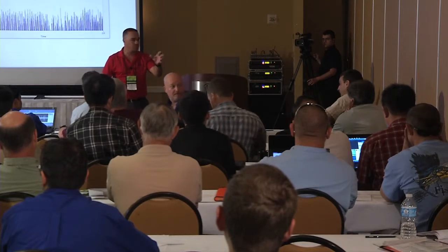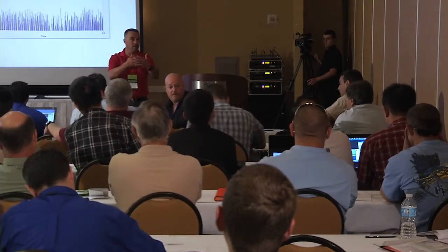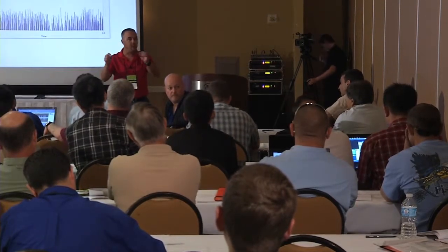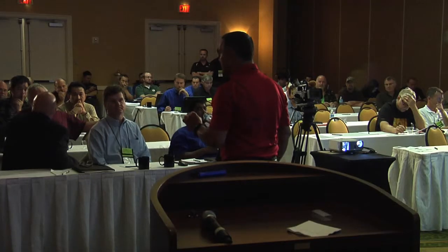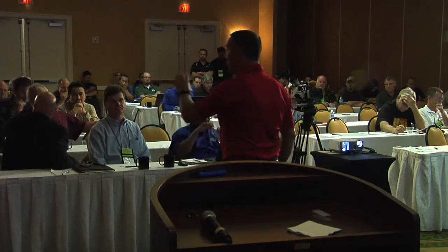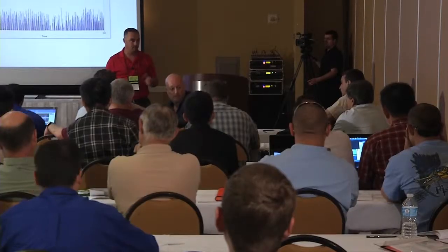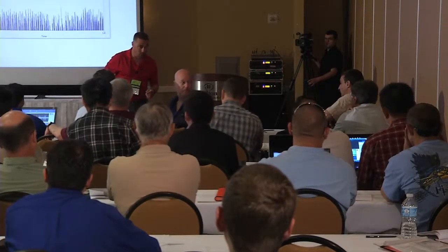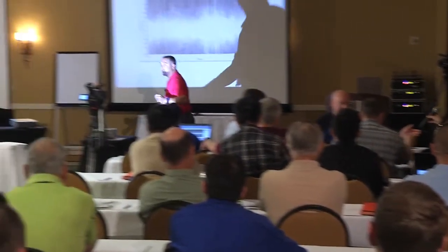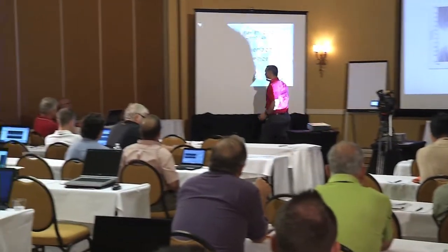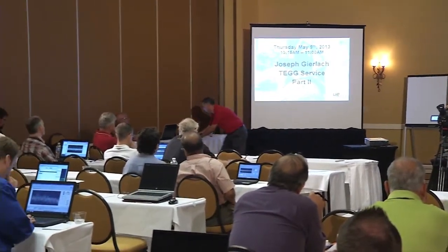exactly. I'm just showing, look, in both of these recordings, they both have some 60 hertz content and a lot of frequency noise. That is an indicator that this fault is electrical in nature. Does that answer the question better? Okay. Any other questions right now? Okay. Let me close this out.